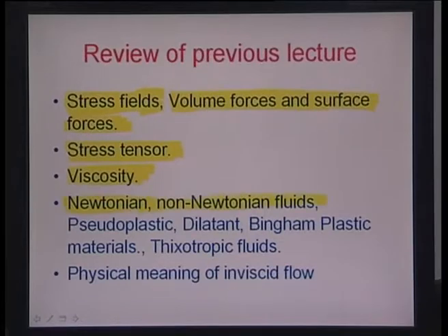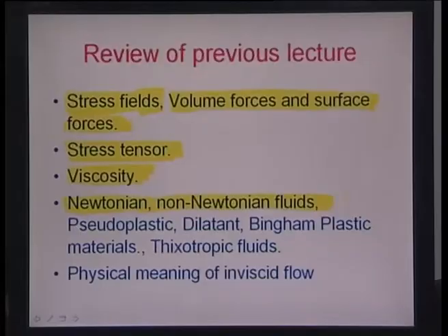Newtonian is where the stress and the velocity gradient are in direct proportion with each other, the constant of proportionality being viscosity, which later got converted into kinematic viscosity, because a better physical idea would be to compare the absolute viscosity values with the density of the medium.